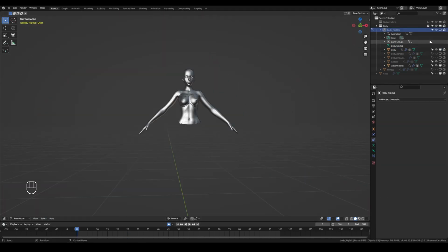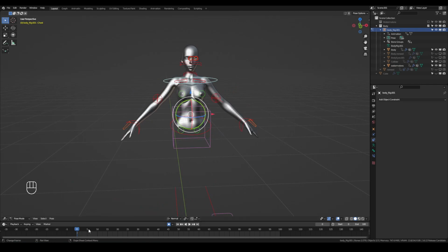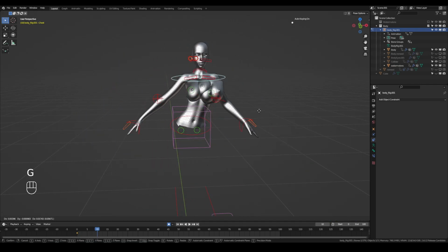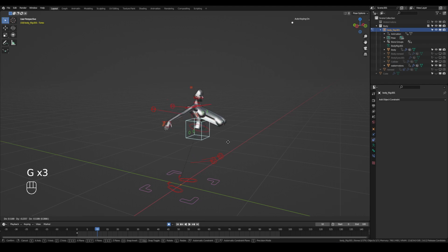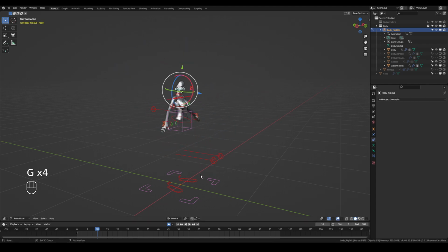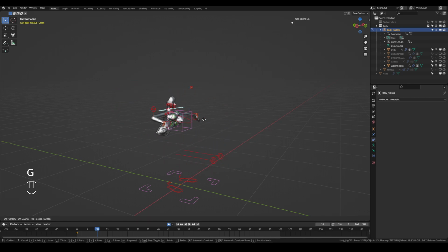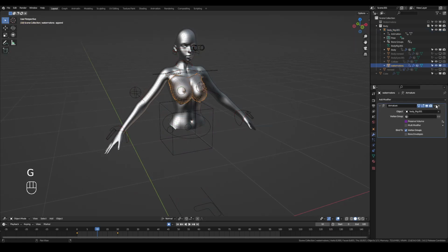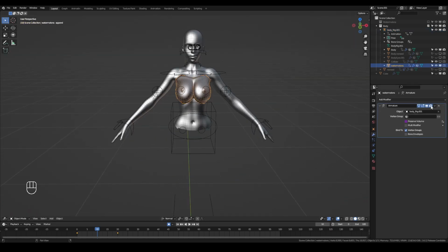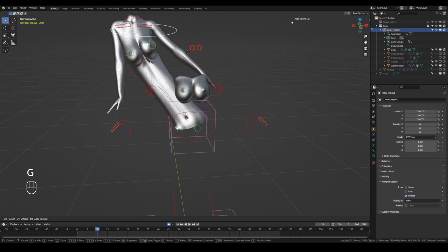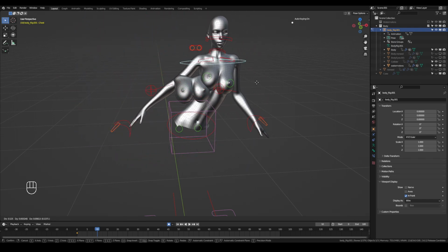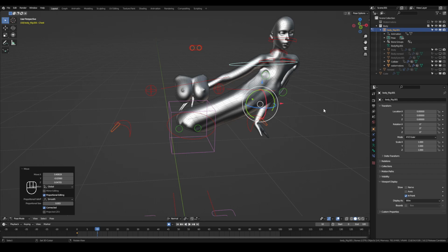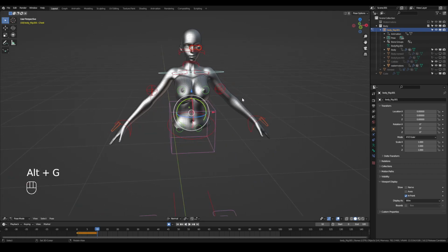The hardest part is over. The only problem left is to fix the wrong deformation. Luckily for you, you don't need to lose brain cells, because I've lost mine once for you. This is caused by the Mesh Deform modifier. It seems like vertex coordinates are stacking from the cloth mesh with the main mesh, and we got this result. Disabling the armature on the cloth mesh solves the problem. But the cloth mesh stays in one place, and this is not acceptable for cloth simulation because it must follow our model and collisions. So we must attach our cloth mesh to the armature in a different way.